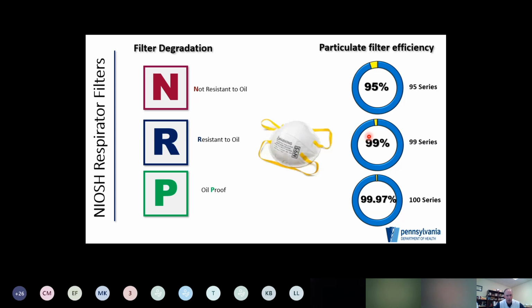Really, it's attributed to primarily two factors. One is that virus particles, while smaller than 0.3 microns in theory, do not tend to exist singularly as a virus particle. Unless you're into some aerosol-generating capacity or specialty research, chances are we don't see virus particles. They attach to things. They bind to respiratory droplets, dust particles, fibers, et cetera, which tend to be larger than 0.3 microns,